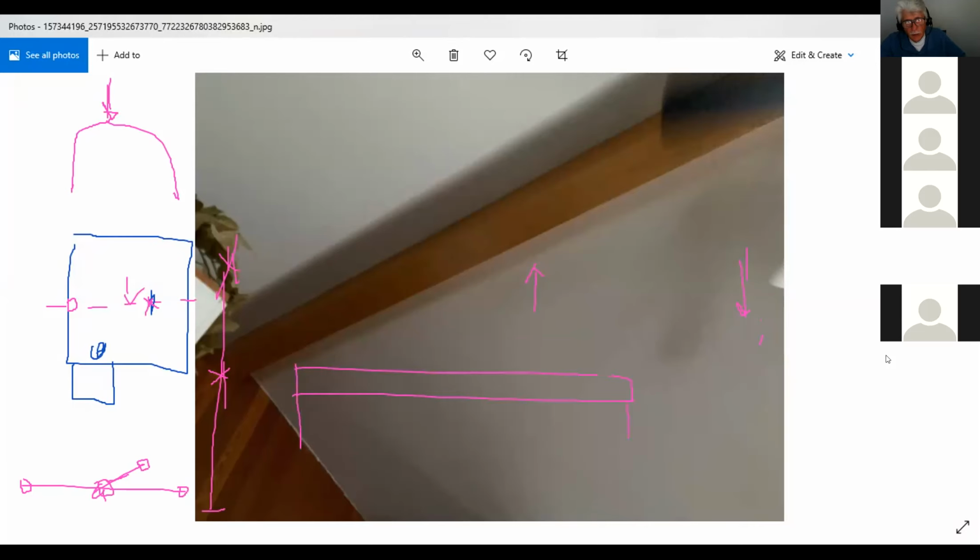Now, do I have one here in between somewhere? That I don't know. You understand? But this is the thing about walls, you have to be careful. The walls could be hiding where the columns are. So this is the beam that you want to modify here that's supporting the floor that you want to modify. Now, if this column here happens to fall on top of the column that you want to modify, because here you said this is where you had your three columns, you understand? And if you want to remove this column, well, it becomes very critical because all this load here has to be carried by the beam that has to be transferred here. So it's a completely different analysis.